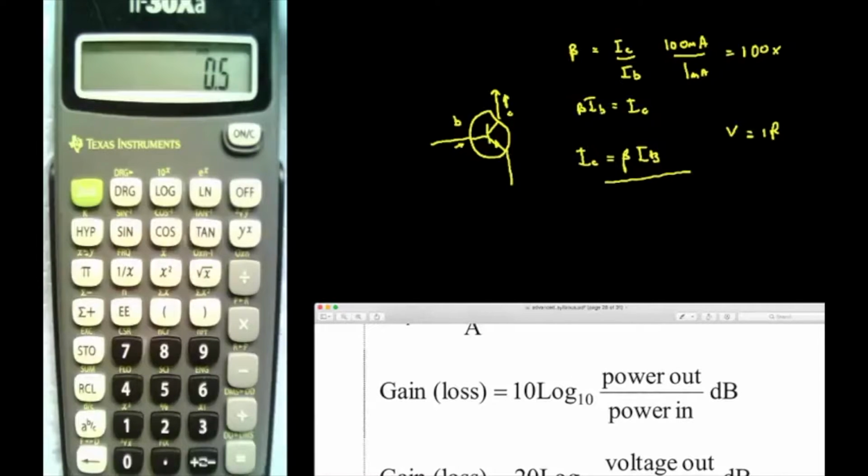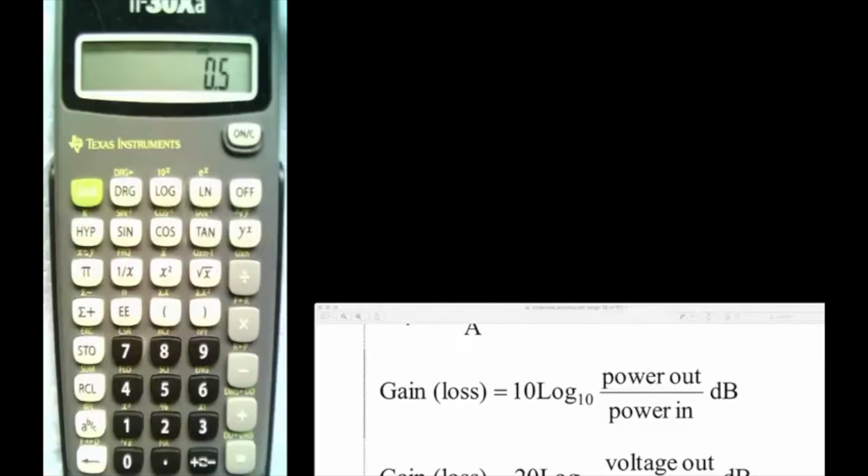In the intermediate course we said that dBs were a logarithmic ratio. Okay, and we said that they always had to be in relation to something. They showed a gain or a loss in relation to something. You had to have a starting value. And the only time you don't, and one is assumed, is where you have an amplifier. And here is the symbol for an amplifier. It has an input and an output, and it could have a gain.